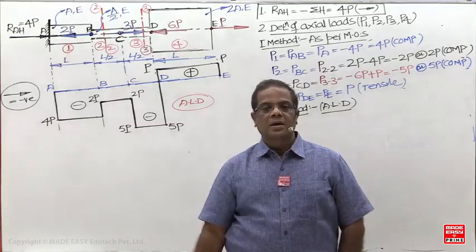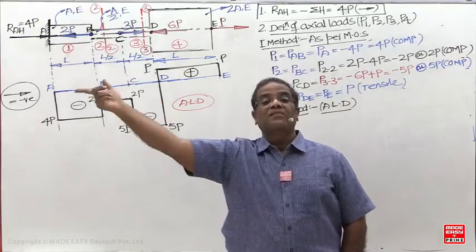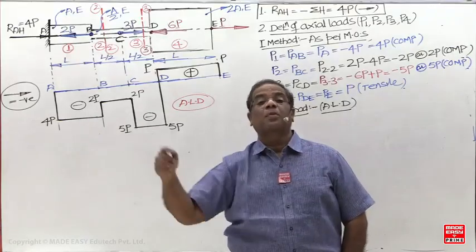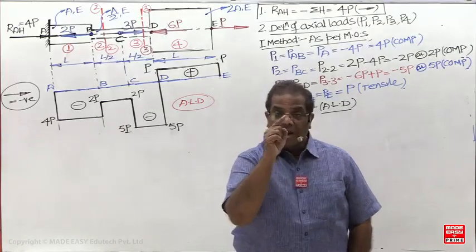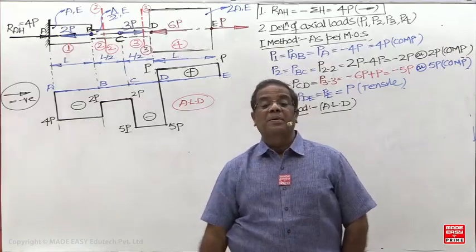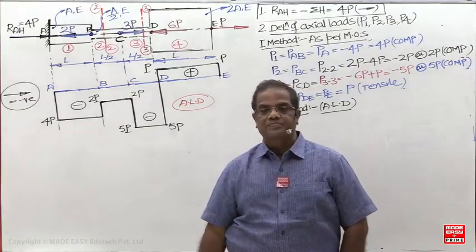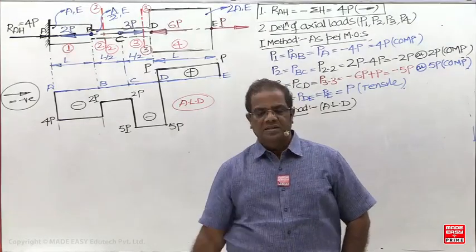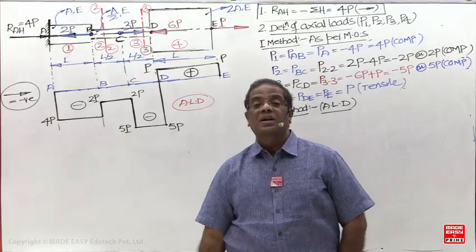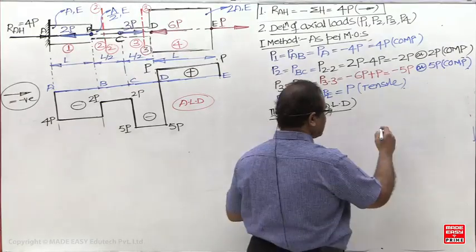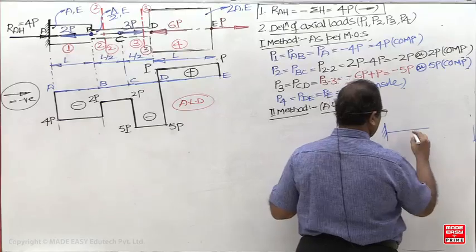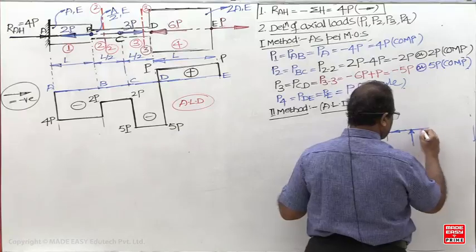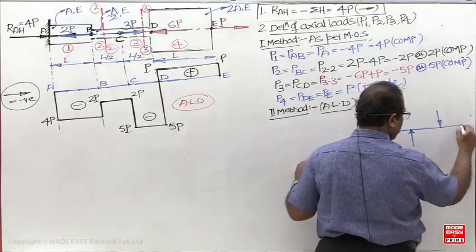That is a cross check now. Number of vertical lines in ALD are equal to number of axial loads on the bar. Number of vertical lines in SFD are equal to number of concentrated point loads on the bar. Number of vertical lines in BMD are equal to number of bending couples or concentrated moments on the bar. Next, number of twisting couples: number of vertical lines in torque diagram are equal to number of twisting couples. Now, in the previous example, this example you just completed, like this you have taken.